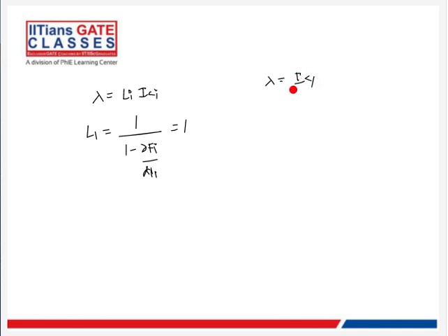So what would be IC1? That is 0.35 Pg1 plus 41, right? So 0.35 P1 plus 41 is equal to 117.6. So if you solve this, what do you get? P1 as 218.8.